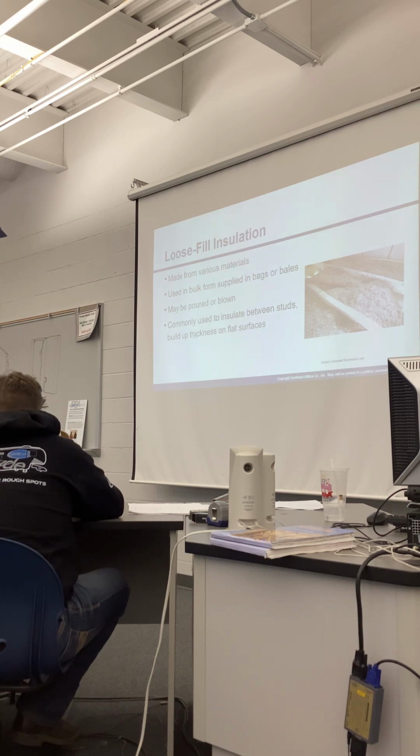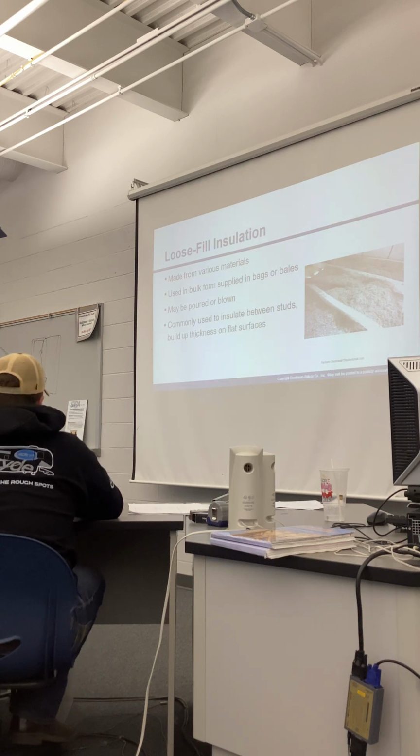So right now in my attic, if I walk in there, I did this because I'm cheap and I would not do it again. I didn't do it on my addition. But if you walk into my attic right now, there's spots that have 2 inches of insulation, there's spots that have 15 inches of insulation because it's blown all around and moved. So I'm not a proponent of this.